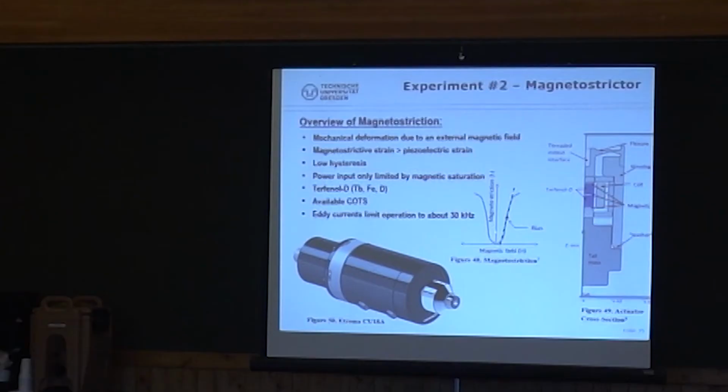This is how magnetostrictive strain varies with the magnetic field. So it's kind of like electrostriction; it's a quadratic effect. For ultrasonic transducers, we want to apply a bias with permanent magnets so that you have a center magnetic field, so that you can go on both sides and stay in the linear range, to have a linear expansion of the material with the magnetic field. Quick question: is the magnetostriction entirely along the axis of the actuator? Yes.